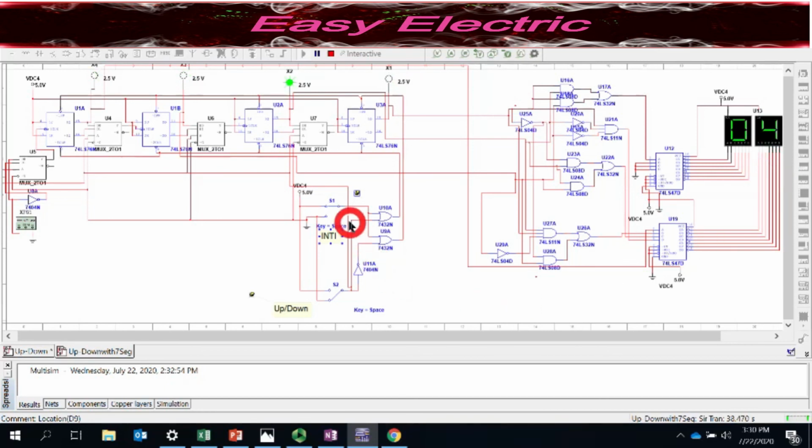So now I put this to the down counter. See, this here should be the down counter, and initialize that. That means it immediately loads 15, because you want the down counter to start at 15. So the initialize is active, it is 15. Then if you deactivate the initialize, it starts counting down 13, 12, 11, 10, 9, 8, 7, 6, 5, 4, 3, 2, 0, and 15. Again, back to 15, okay?